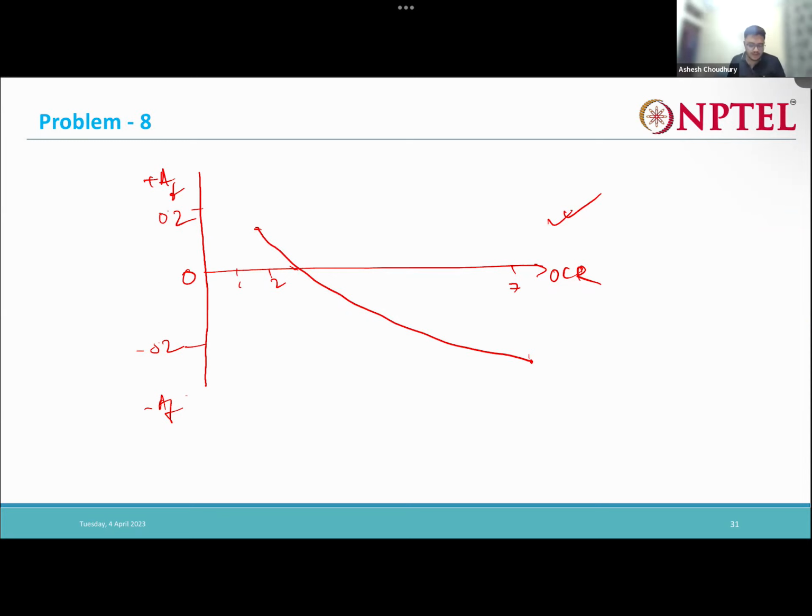At this point we are getting 0.13, so it is neither completely over consolidated nor completely normally consolidated. It is something in between. For NC, the A value is between 0.5 and 1, and for OC, it is between minus 0.5 and 0.